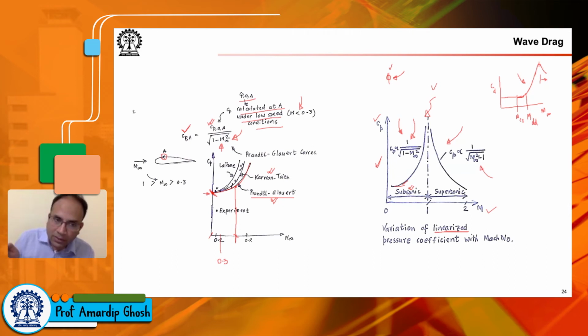We know that the Mach drag divergence comes behind the Mach critical. So if you have a way in which you can find the Mach critical, then it's of some use. That is, if you do not cross your Mach critical, or at least you know the margin that you have between Mach critical and Mach drag divergence, then you at least have some safety in terms of when you are going to hit that very large rise in CD. Once again, that rise in CD, as you see here, is not infinite. If you see, your Cp being influenced by this 1 by square root of 1 minus M infinity squared could have become infinite at M infinity equal to 1.